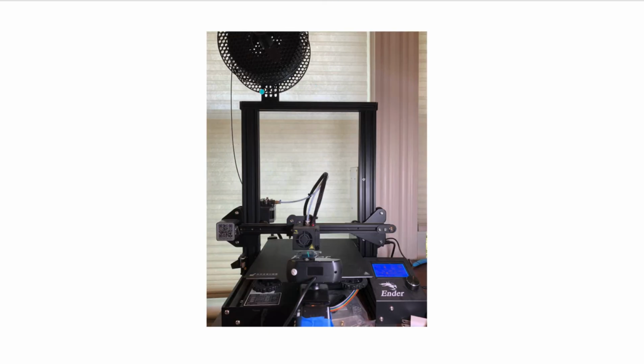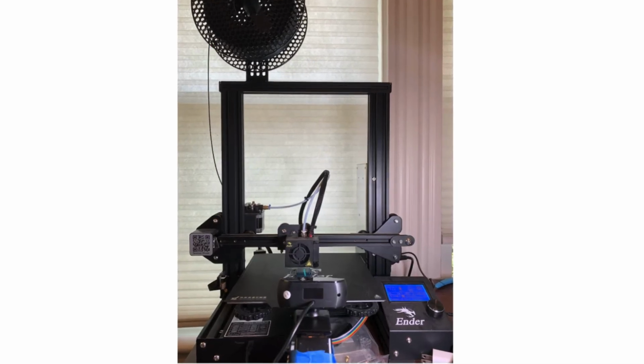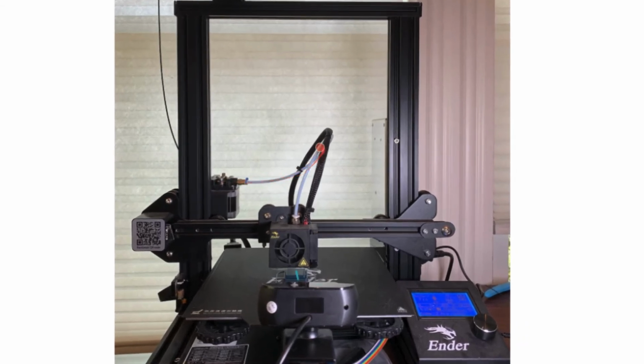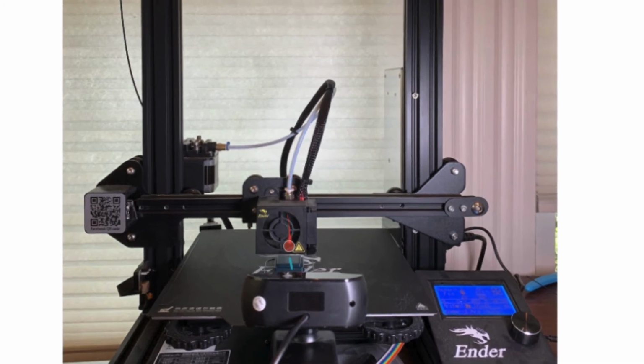Okay, let's dive a little bit into how FDM works. As I said before, it takes a roll of plastic, feeds it into an extruder, which heats it up, and then spits it out in a thin line like this, and draws each layer. Let's look at what an actual 3D printer looks like. So here's the roll of plastic, and you can see the filament comes down through here. It actually goes through the motor that pushes it here. It goes through this tube and down in where it gets heated up, and then it gets spit out the bottom there, right here, drawing it layer by layer.